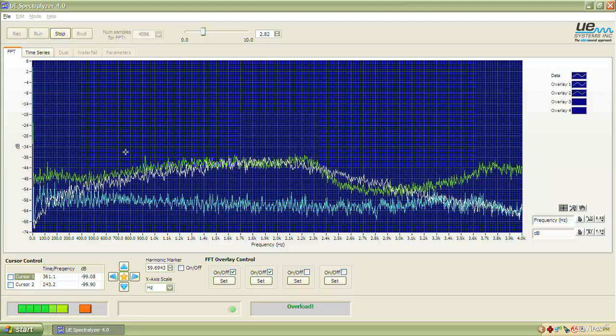So if you want to email this sound file off, you need to email the actual sound file after you have converted it like I showed you, and then do this, reports, the screen capture, and then come back to File, Save As, HTML file, save it somewhere easily accessed on your computer, and then grab that. So you would actually send two attachments, the WAV file itself and then the screen capture showing what it looked like when you analyzed it. So remember, if you just send this, they don't have any sound, it's just a picture.